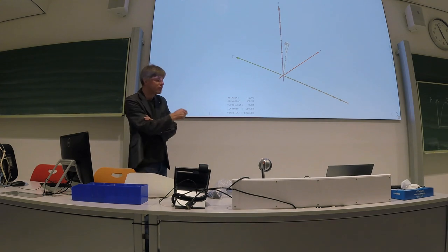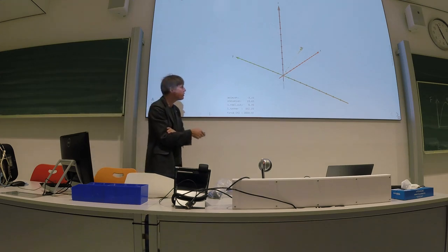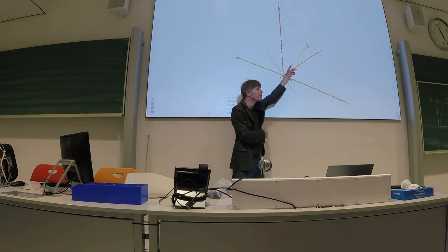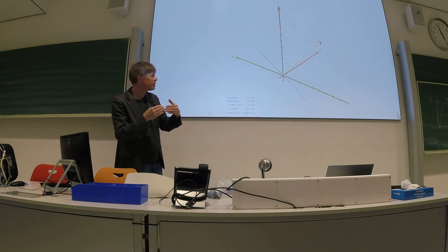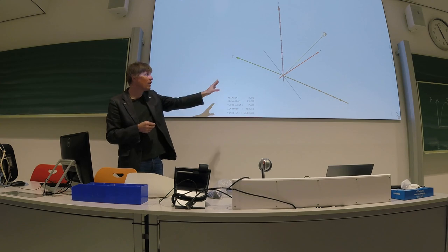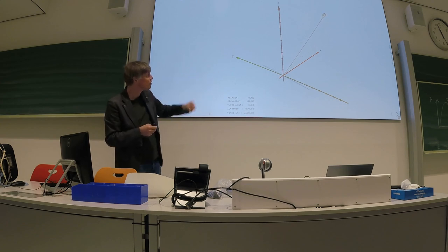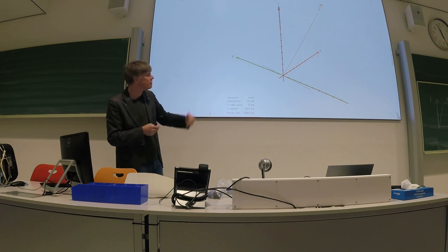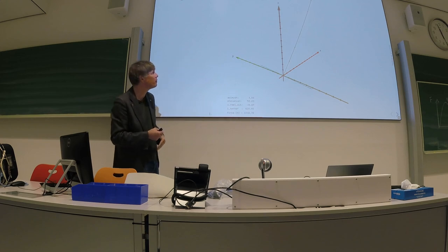This is a simulation of a pumping cycle with a dynamic tool. You see in this dynamic tool that we discretized also the tether, and if you look closely you see that the tether is sagging a little bit, especially once we go from reel out, which is now, into reel in, which is actually now. Then the kite typically sags, because there is a force difference between reel out and reel in.